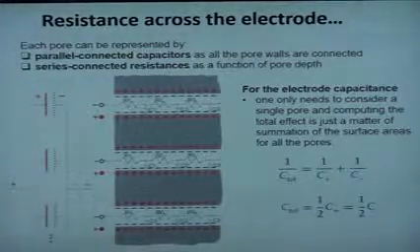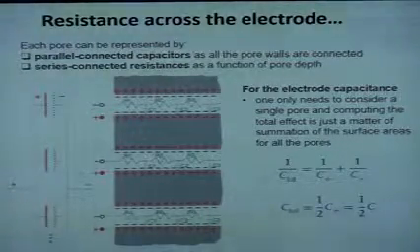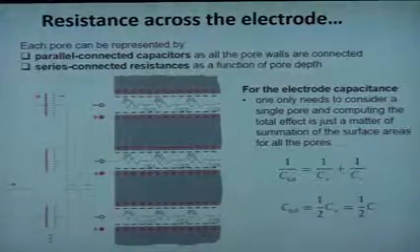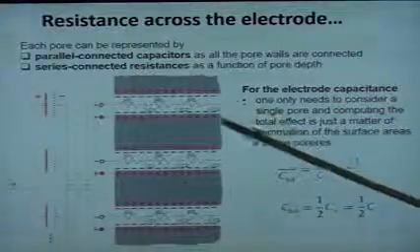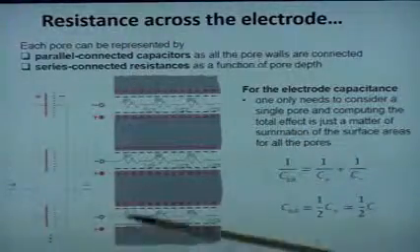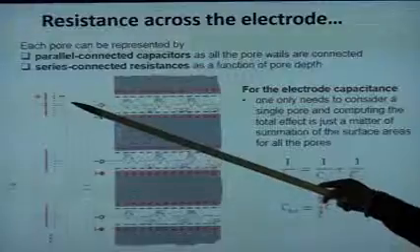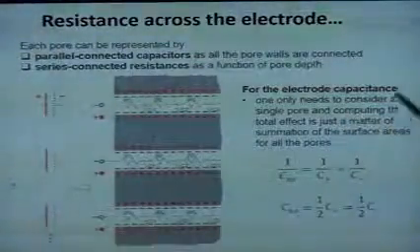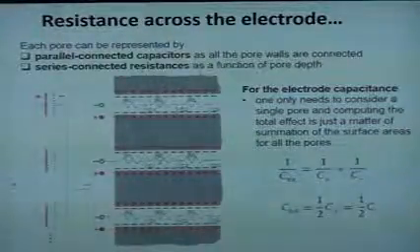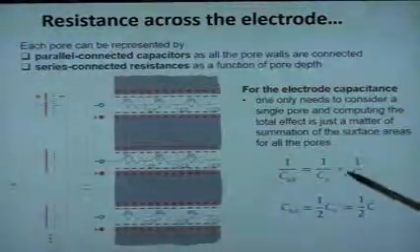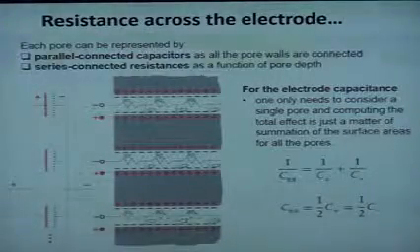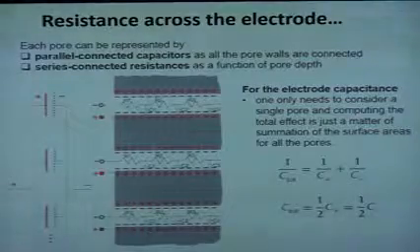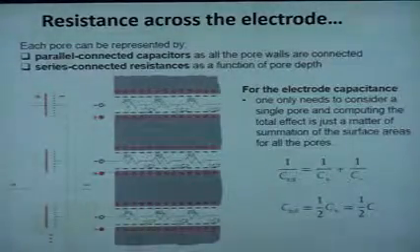That individually acts like a capacitor, and then there are multiple resistances across each pore. So this can be represented by a simple diagram where each individual pore is acting like a capacitor. When you want to calculate theoretically the capacitance of an electrode, it is nothing but summed over different pores. So you can calculate over one pore and then add it up to get the total capacitance.